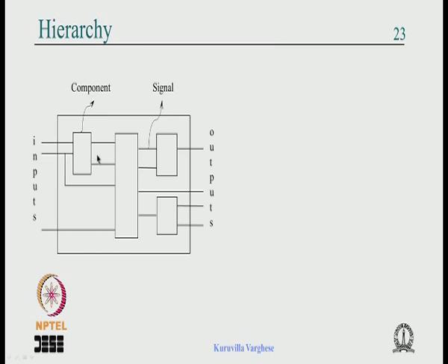The idea is that you are going to put another component and you are going to connect using some signal, and you know that VHDL is a strict data type checking language. So if you are connecting an output to an input, if the output is of the type standard logic, then the input also has to be standard logic,